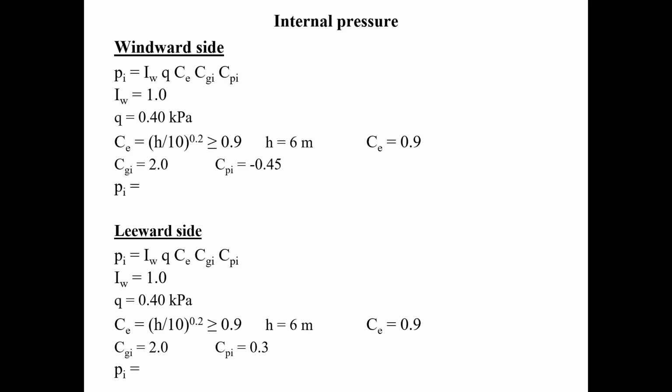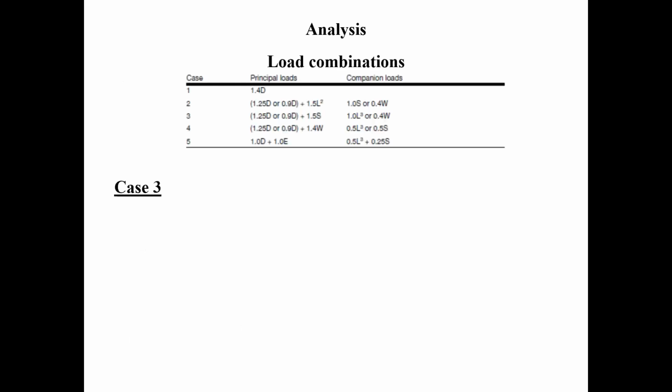Just a quick question. So we do exactly what we did in class today? We go case number 3 and case number 4? Yeah. You do case number 3. You have the value here. The only difference is that this is already in kilonewtons. Do you have to do anything else? No. The only thing you have to do is get this here. This is right now in kilopascals. How do you convert it to kilonewtons per meter? You have to multiply by the tributary width.